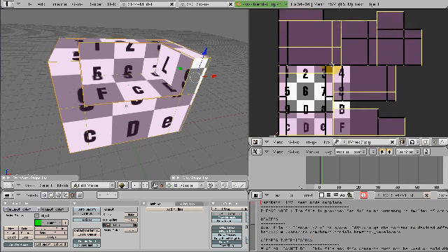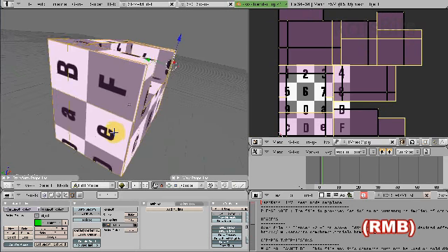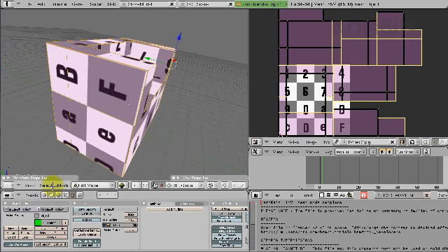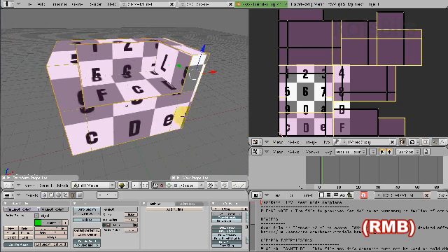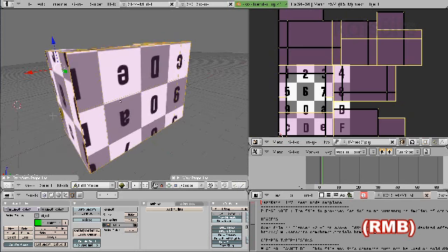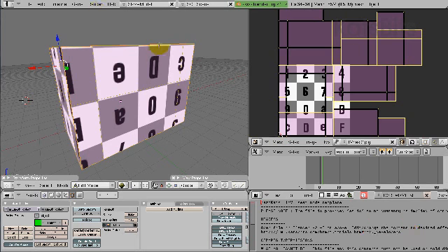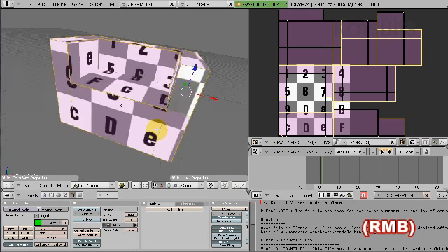Otherwise, if, for instance, this were a chair with a fabric texture applied to it that had a grain to the fabric, like corduroy, you'd want the UV map to be set up in such a way that, regardless of what you were looking at on the mesh, the grain was always facing in the right direction relative to the chair and the fabric.